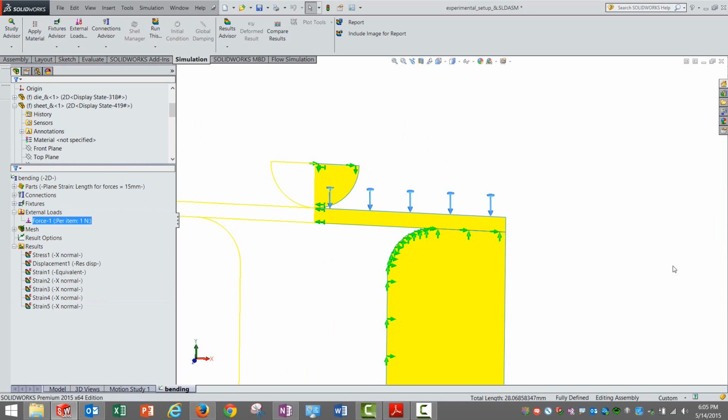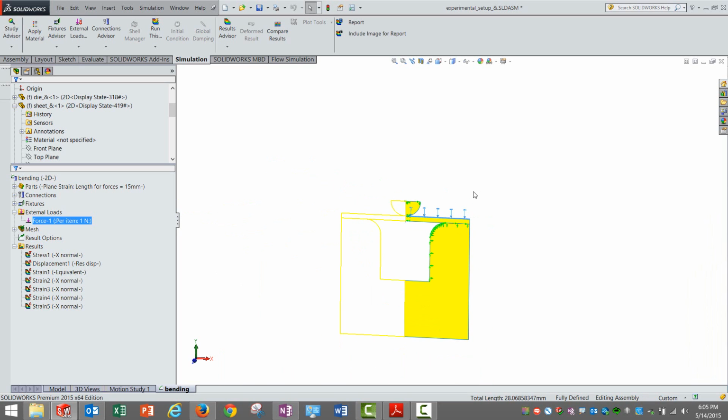So this is a funny thing. I have seen users making many mistakes. Some people even apply restraints over there, which is incorrect, because there can be a certain amount of movement in the x direction for this part. The specimen can move in that direction, so we cannot use that. So keep those in mind, and this is an intelligent way of applying or stabilizing the specimen.